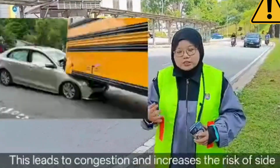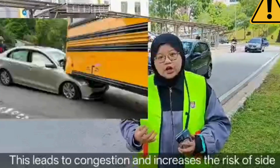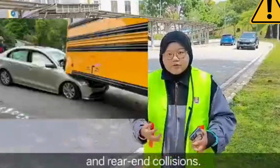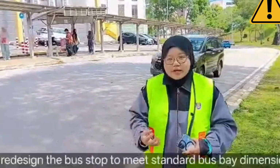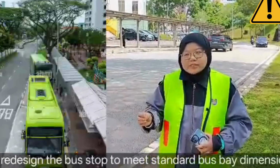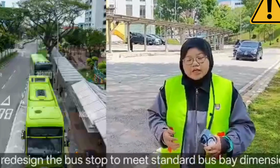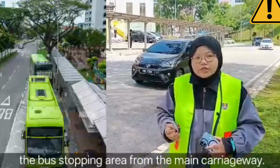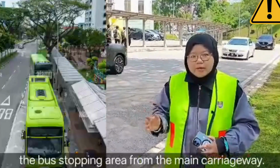This leads to congestion and increases the risk of side and rear-end collisions. Therefore, the mitigation is to redesign the bus stop area to meet the standard busway dimensions and improve road marking to clearly separate the main road and the bus stop area.